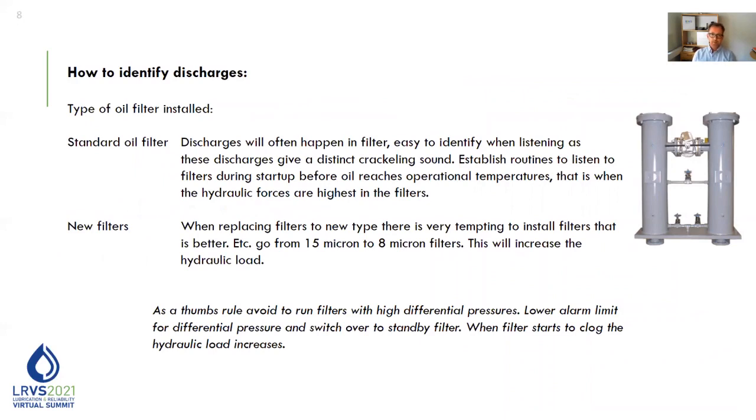Discharges will often happen in the oil filter, especially if the machine is run with the filter types that were installed when the machine was new 20 to 30 years ago. We ask our clients to listen to their filters. If you hear a very distinct crackling sound from your filters, then you have discharges within them. Especially during startup, we advise clients to follow up their filters, because before the oil reaches its operational temperature, if you have discharges, then it's very easy to hear that crackling sound.